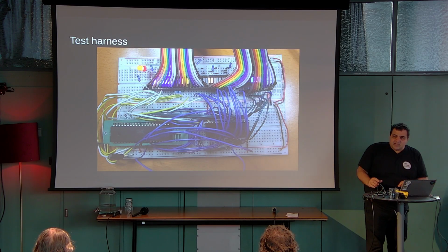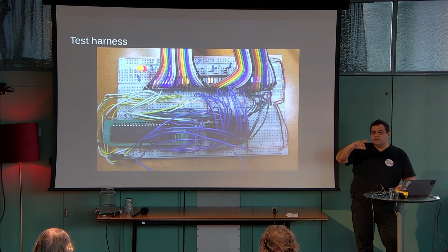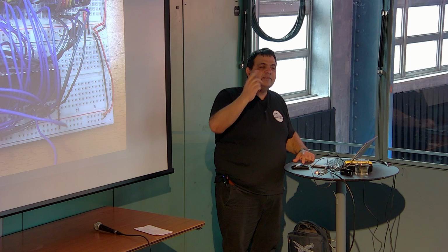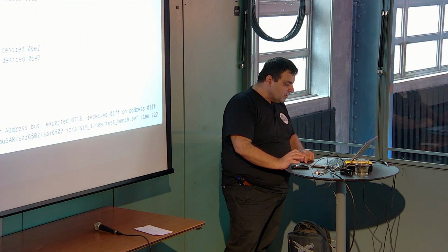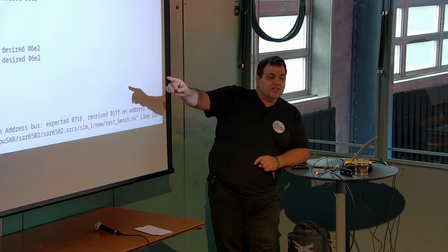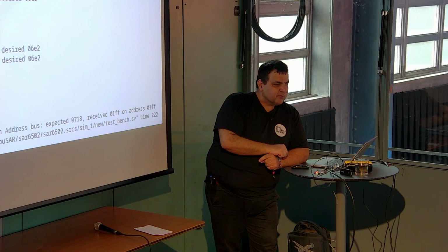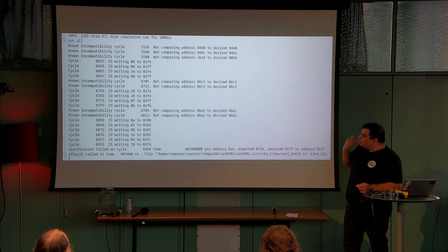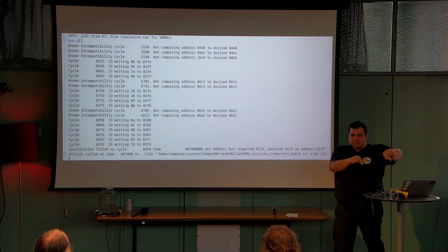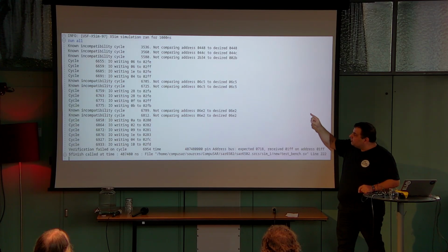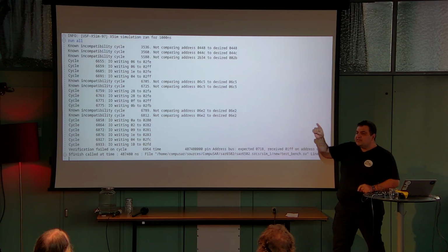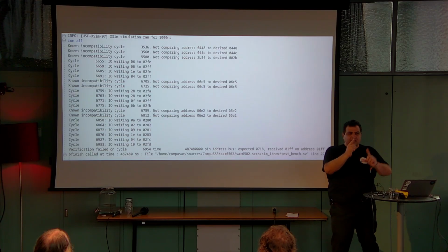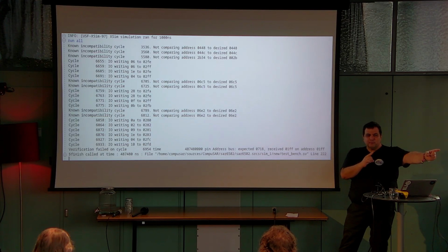And the nice thing is, if you then replicate this program from Python and you write it again in SystemVerilog, you can have automatic verification of your design within the simulator. So you load the program into the simulator, and you run it on your own CPU, and you have an infrastructure that makes sure that every single cycle you're doing the same as the authentic CPU.